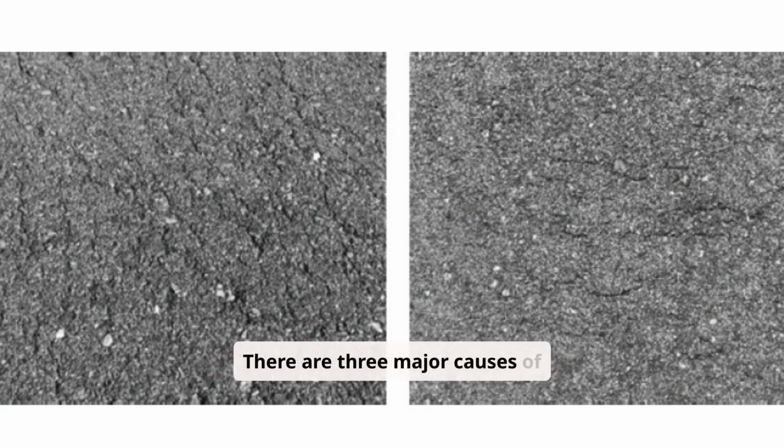There are 3 major causes of microcracking. Excessive pavement deflection during compaction creates surface tension in the mat, causing tiny fissures or cracks on the surface. Tender mixes tend to shove when compacted and create surface tension in the mat, causing tiny fissures or cracks on the surface. Compacting a cool mat shows microcracks, as a cool mat is stiff.